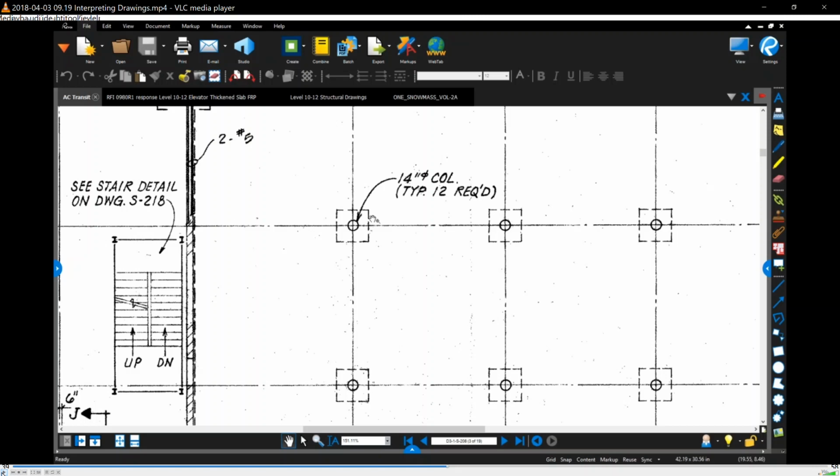Feet, or 48 inches by 48 inches, and then the contractor used a 1.5 inch wide piece of a 2x material, basically, to form the edges of that drop cap. And so you take off 1.5 inches, that's the actual dimension of a 2x, on either side, so 3 inches total, so 48 inches minus 3 inches equals 45.